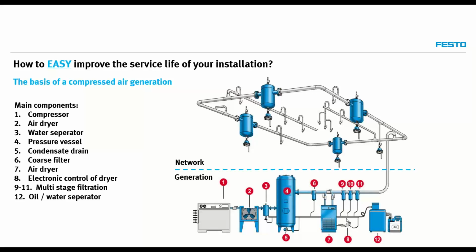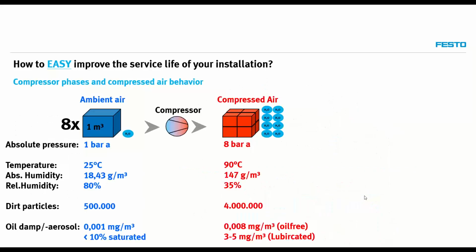Last but not least, all the water which is collected during the pre-filtration and the conditioning steps needs to be disposed of. In many cases there is a possibility of oil, so there might also be an oil water separator, so you can easily dump your condensate water to a sewage line, and the oil can be separated from that.